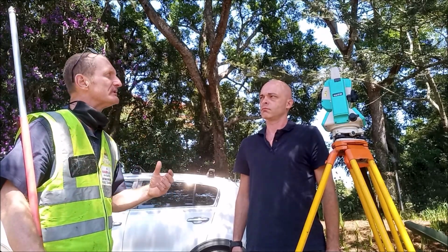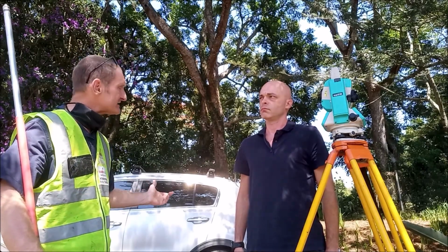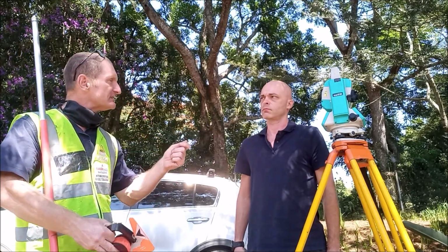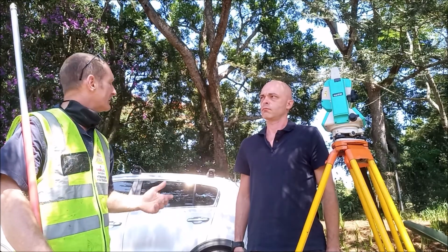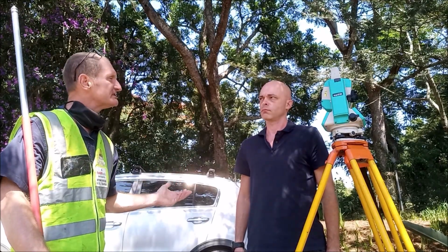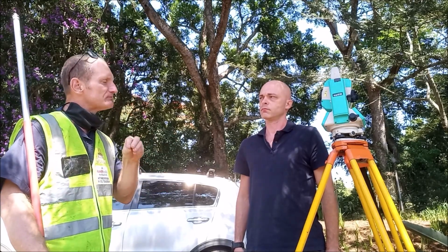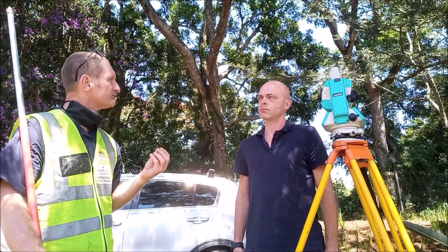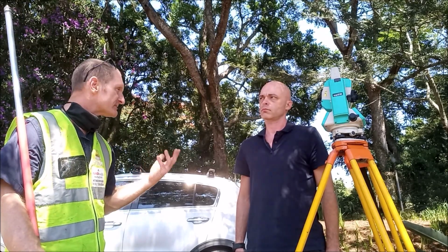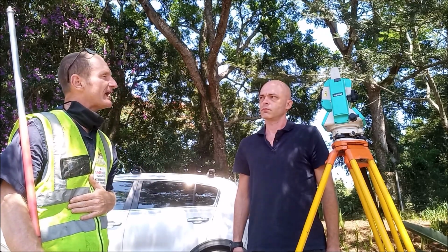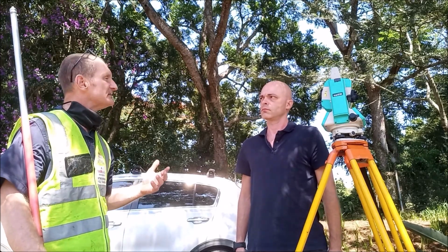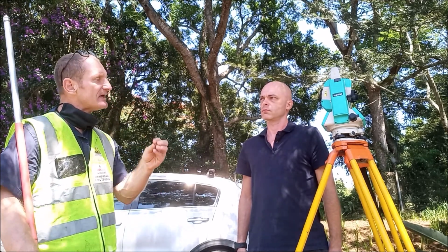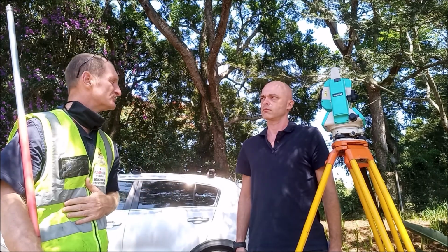However, on modern vehicles we have things like wheel speed sensors, which are measuring the rotation of the tire or the wheel, or we have a steering angle sensor, or for instance we may have a delta V sensor, a change in velocity sensor. All of these parameters that are measured by multiple different devices on the vehicle also provide us with measured, quantified values from the vehicle. As an example, we would very often look at a wheel speed sensor. So we could see at certain time frames what rotational speed the wheel is doing. We can relate that back through gear ratios and come to speed ranges.